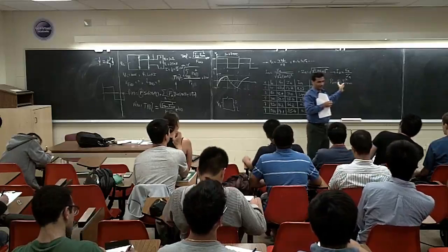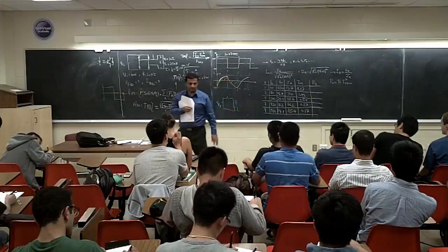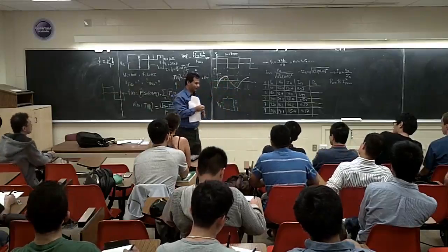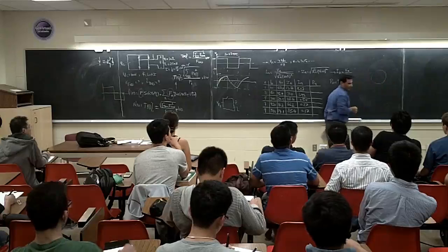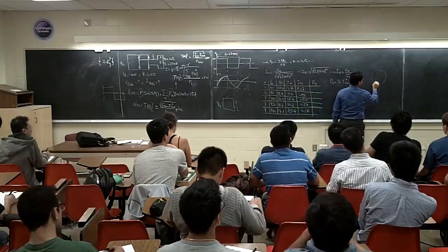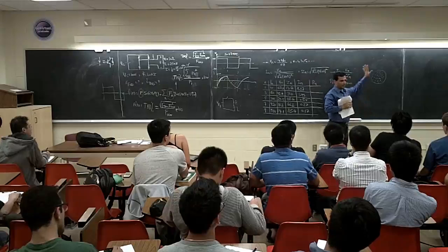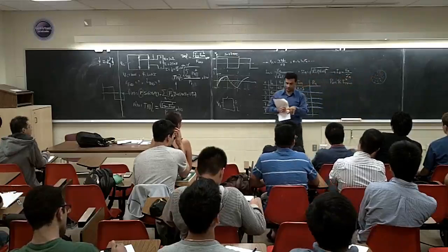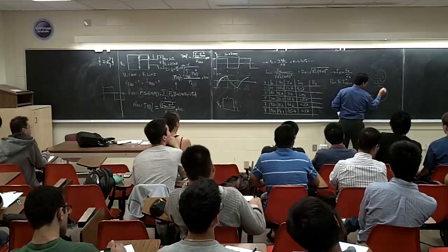We're not going to go through that one here. But when you get to very high frequencies, like, I don't know, kilohertz, 20 kilohertz, we call it the skin effect. You know that, right? Let's say this is a cross section of a conductor. If you have a DC current, it's going to go uniformly through everything, right? The current is uniformly distributed and goes through all of the conductor. But if it's an AC current, if you look at the current, it's going to be like this. Here you are going to have more.